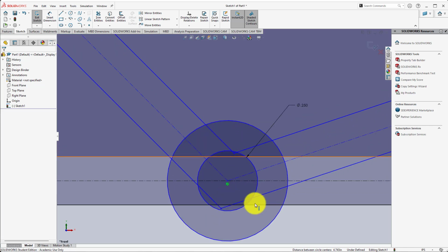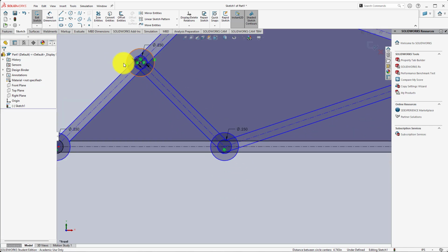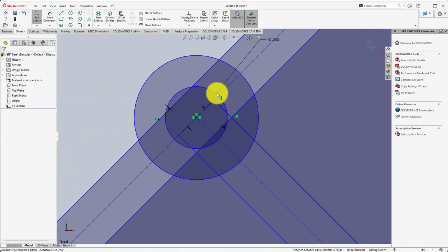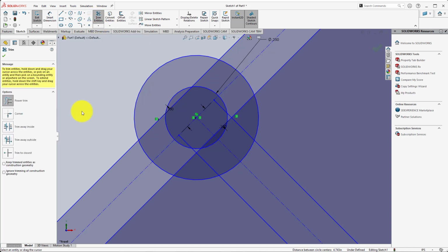going to want to do is I'm going to come down. Let's see, where do we want to do? Let's do it right here on this one. I'm going to come in here and I'm going to trim away the things I don't want to have. So this member, I'm going to have the material coming this way. It's going to go around the part, making the hole, and it's going to come down here to this member this way, and it's going to go up to this member. So we're going to use trim to trim the things we don't want to have.